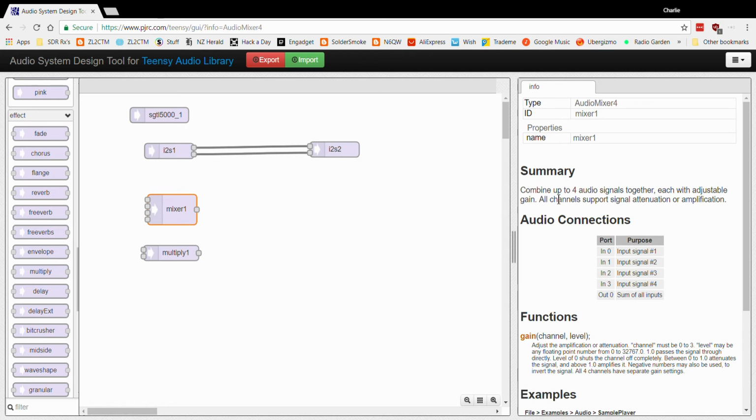If I assign a gain of 1, I've got maximum input. And if I gave it -1, I've actually inverted the input. That'll become very useful later on when we start using our phasing technique for eliminating the unwanted sideband. That'll become very important indeed.